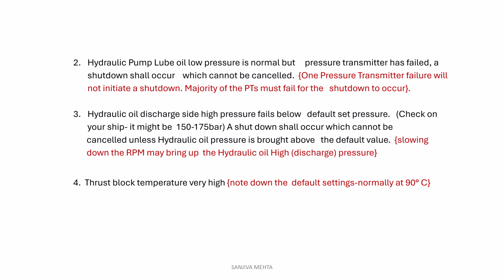Thrust block temperature very high, but these are non-cancelable shutdowns. Note down the default setting. Normally it's 90 degrees. Thrust block temperature high, there will be a non-cancelable shutdown. All right.